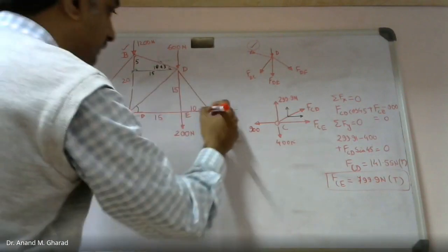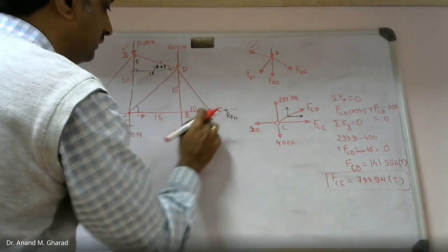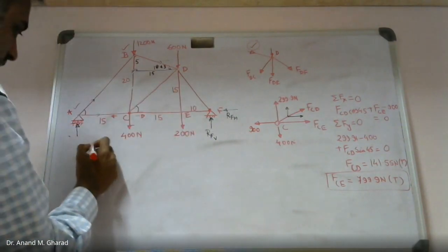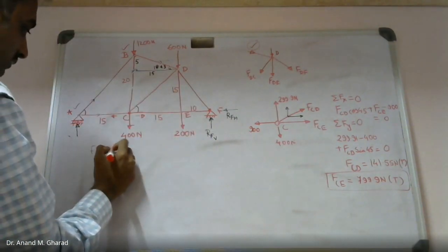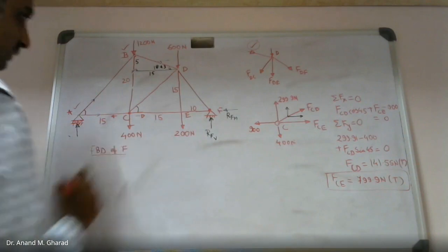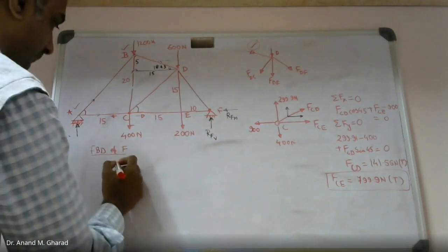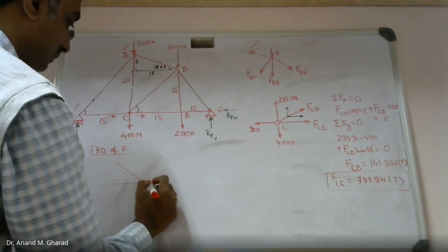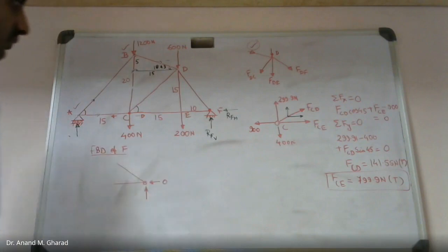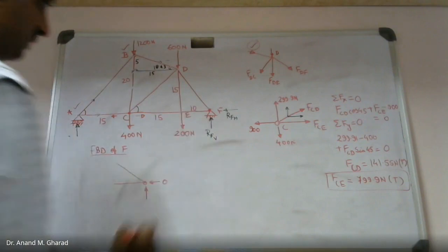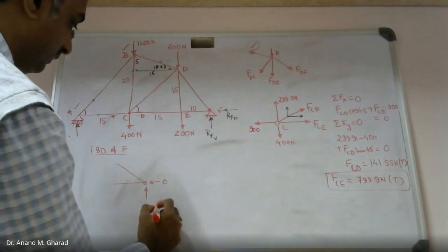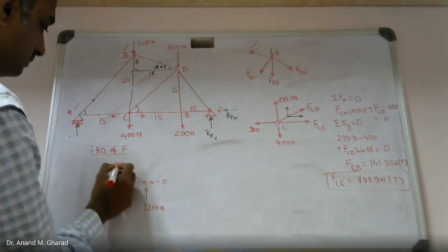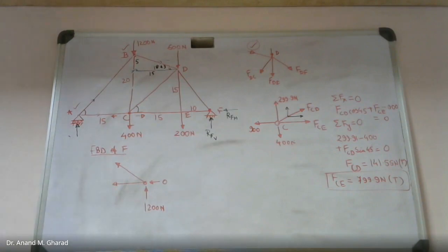But before that, if you try to identify the forces with respect to FBD of joint F, let's see what happens. This is 0 force. We have already found out. This RFB, it was 1200 Newton. Let me consider the 2 values to be tension.